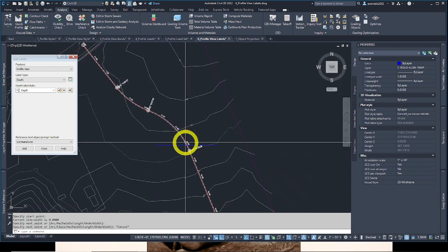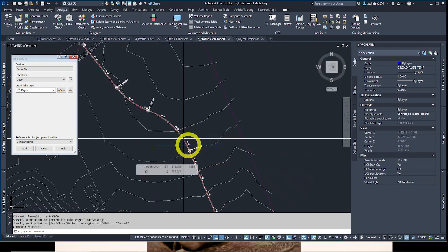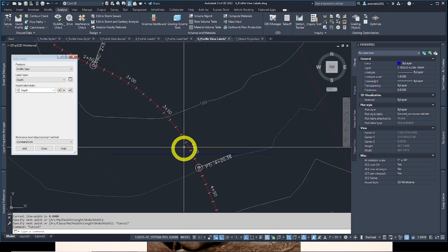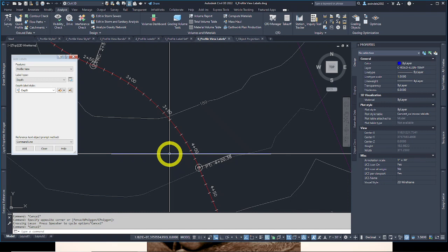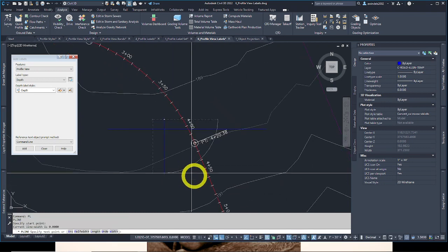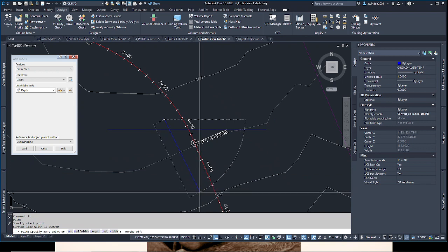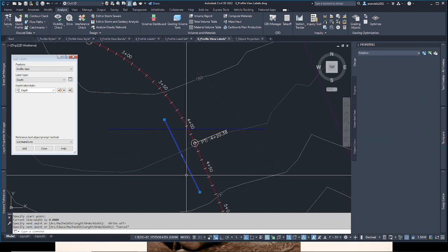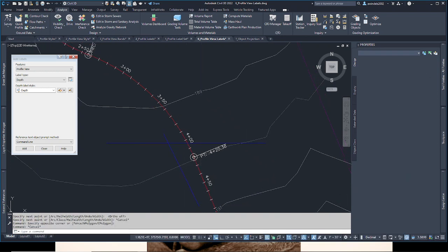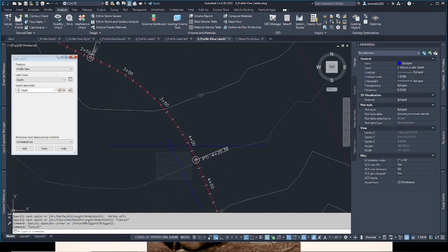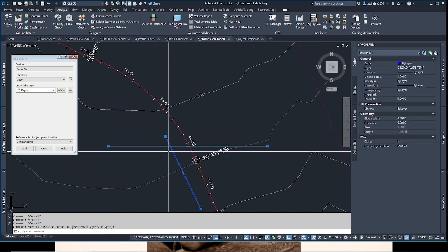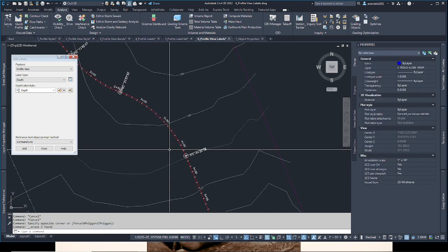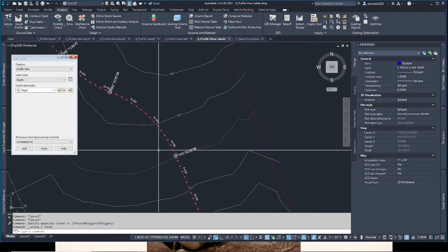a profile view, this profile view runs parallel with this alignment. So if this projected object that crosses our profile view in alignment is not parallel with it, meaning it's not going this general direction, it's going to be distorted. This is more parallel-ish. This one is going to show in kind of an odd little squiggly line across. That's just because it's not parallel with the alignment and profile. You just got to keep that in mind with some objects. They're not always going to go parallel.